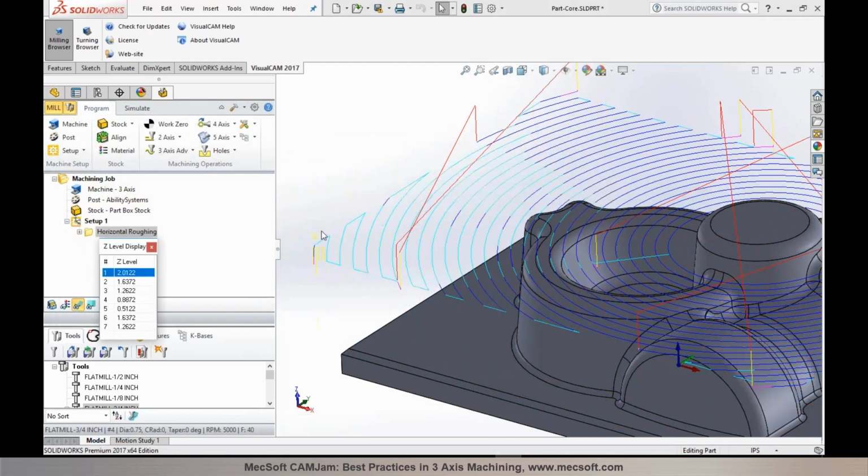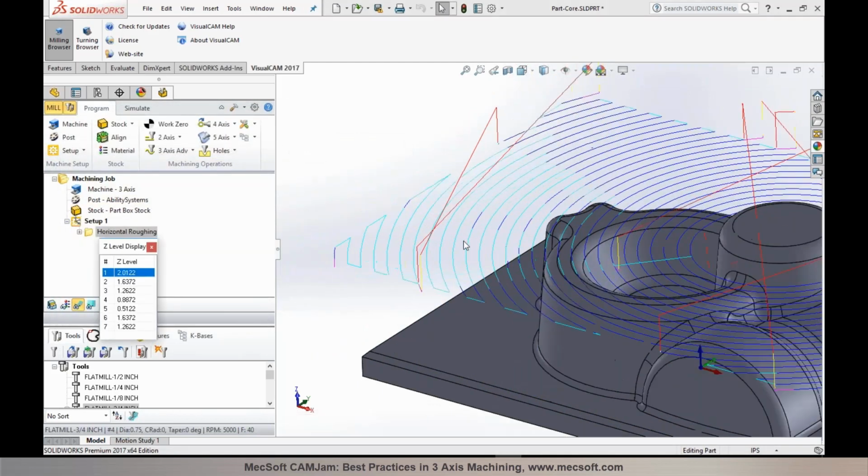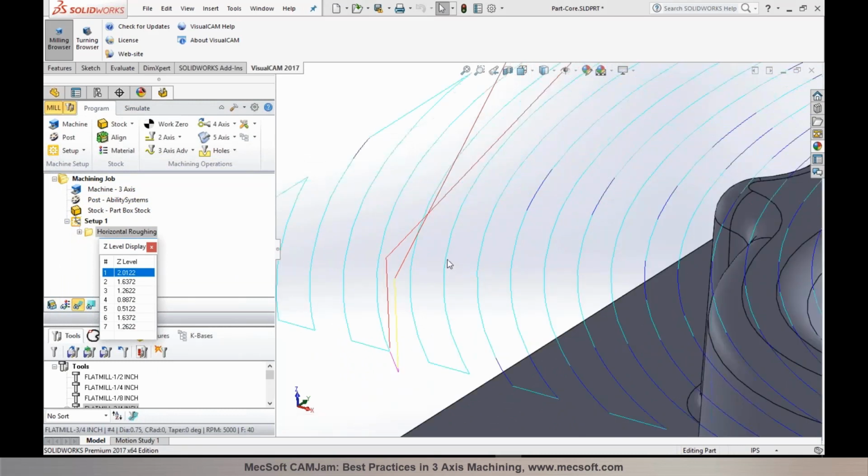As you examine the toolpaths, you will see that the distance between each motion is much smaller, resulting in higher accuracy. The in-tolerance and out-tolerance settings allow you to control the tolerance, or how much you can cut into the net shape. The in-tolerance represents the maximum thickness of material that can be removed from your stock layer.